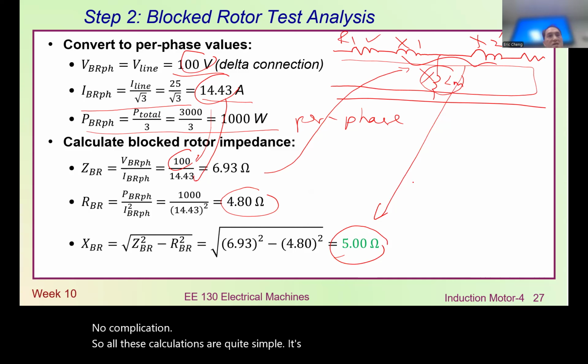So that's the key point we'd like to show you, how we can use the so-called open circuit test or the no-load test and also the blocked rotor test. The blocked rotor test sometimes we also call the locked rotor test.